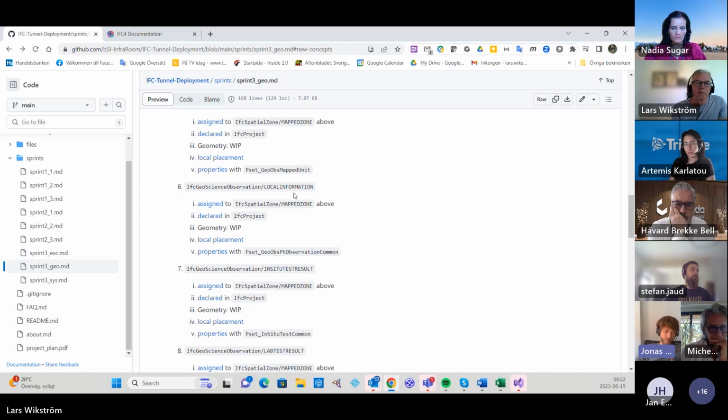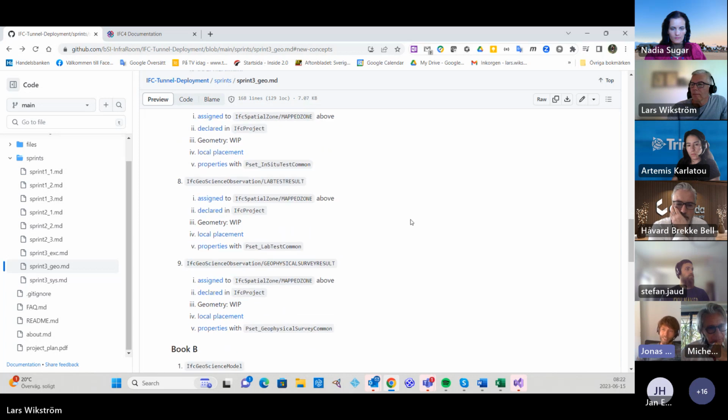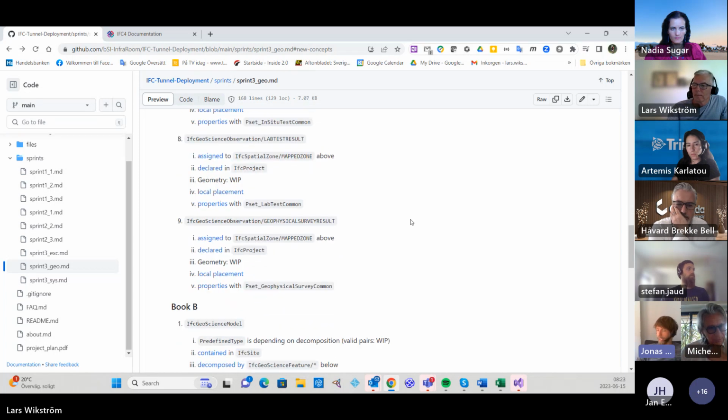And then if you find something in the field and you say it's sand, okay, you note this. Then you take a sample, you send it to the laboratory, and you get back the result. And this says, okay, in fact, it's not really sand, it's mostly silt, and it's sandy silt, and you get a grain size distribution and so on. So this would be the information that you can model as a lab test result. So there are several vehicles, let's say, that can carry your information.